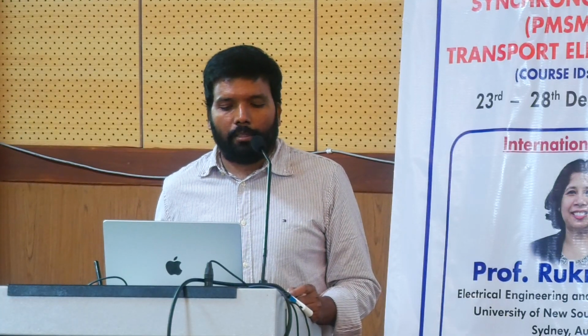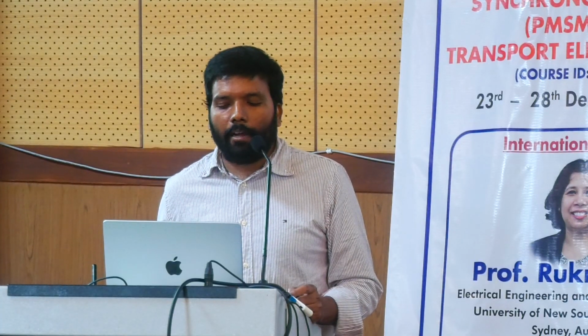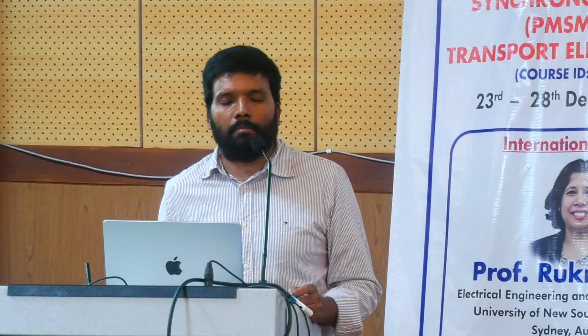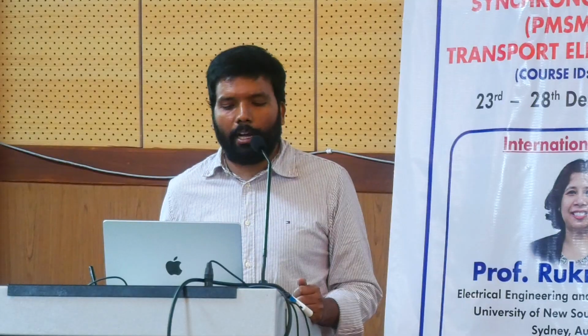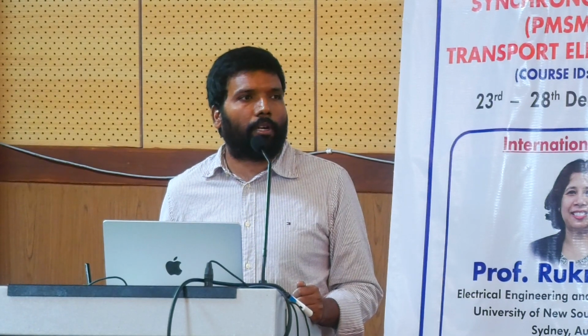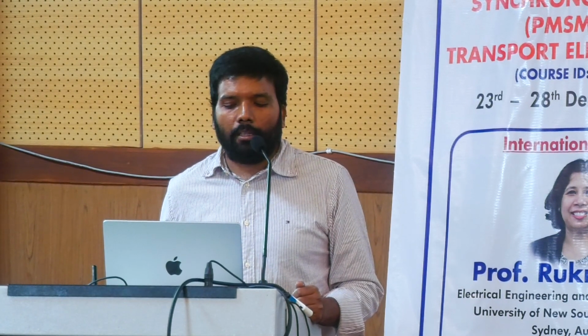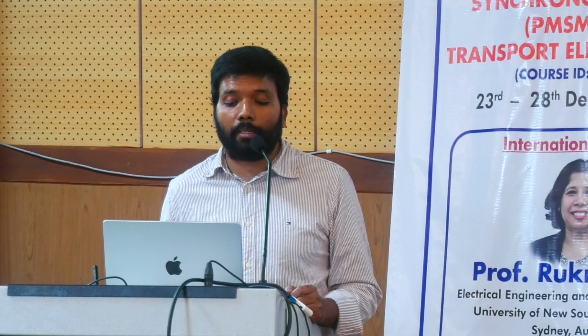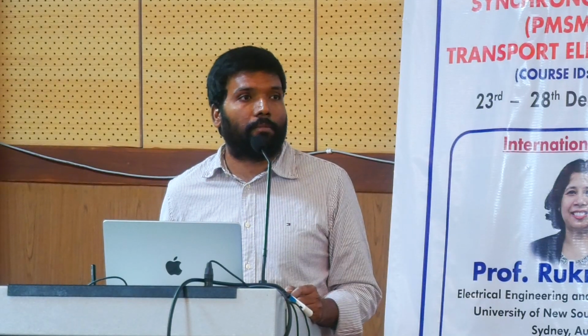Now here, I will take a reference phasor. Now, this is my requirement: I want to change the three-phase vectors into two-phase vectors. Whenever you want to change these vectors from three-phase to two-phase, you need to take a common reference. This is very important. The good thing here is the reference phasor. For understanding purposes, here I have taken the reference phasor exactly in phase with the A axis.